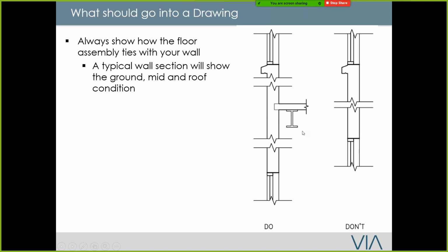That way, the contractor will see this and say, okay, how is this going to tie in or relate to this? If you show it, it means that this is a clear story. That's what it represents. So if you have a floor in between, just show it properly. Otherwise it just tells the contractor there's missing information from the floor. Okay, just avoid that.